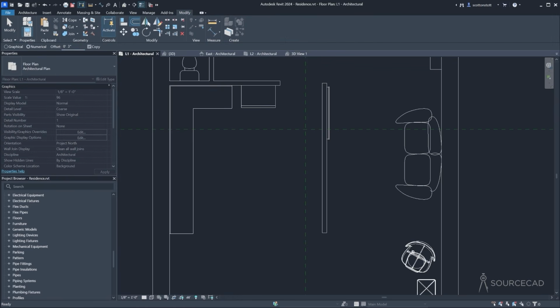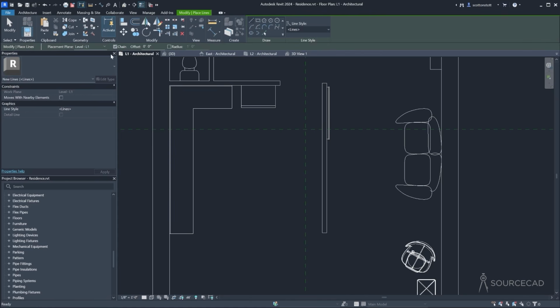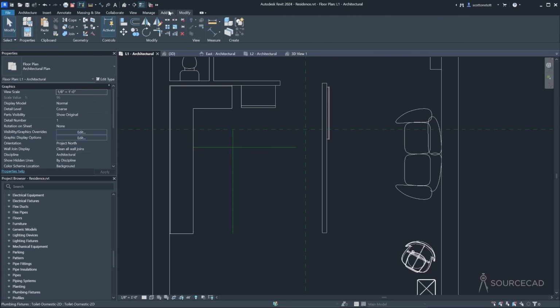I'm going to offset that 3'6" from this line here. So first of all, before I offset, I need to just draw in the line. And instead of using the offset tool, I'm going to do it here, 3'6". And that allows me to actually draw that offset from the line I'm tracing over. I can do that again here. By pressing the space bar, I can get it to offset on one side or the other. And I'm doing that so that I have a corridor around the island with ample space. So it's 3'6". I can then trim these two together.